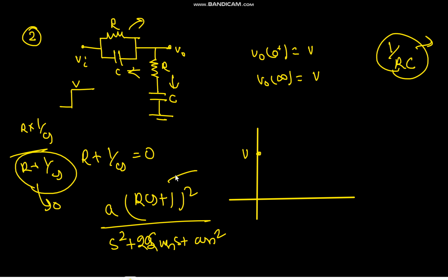So here you have two zeros and two poles. So you can't really tell intuitively how the response looks like. Okay, you can tell one thing, like it's an overdamped system, right? Overdamped system you can tell, because the same condition, like it will have two different poles, that two real, like there wouldn't be any imaginary poles. Real poles would be there, and that two on real axis, and that two different, not the same. Okay, so you can tell it's an overdamped system.